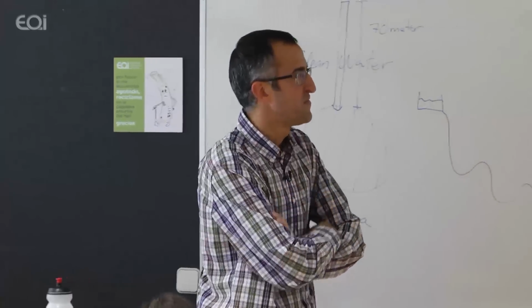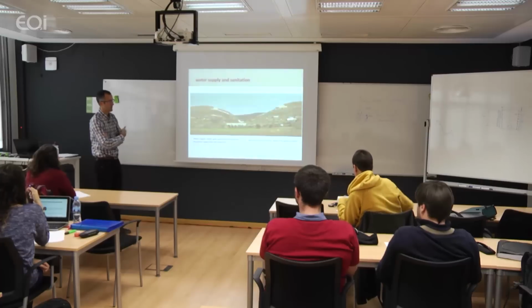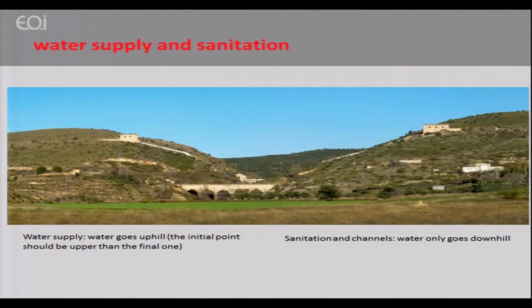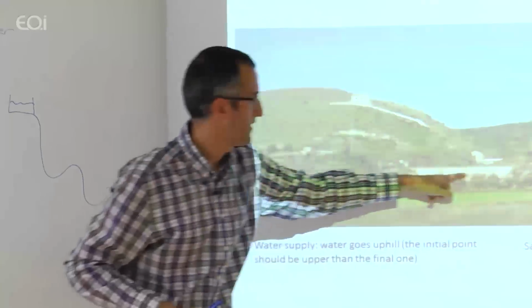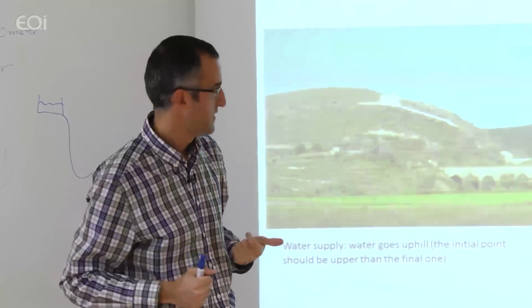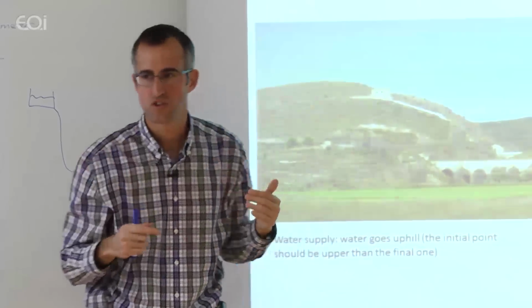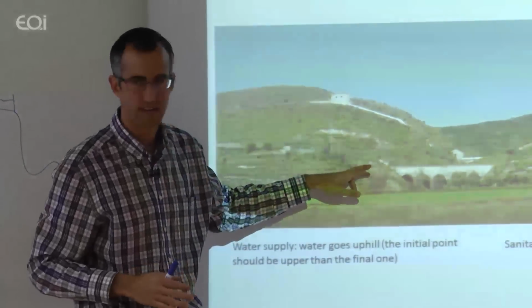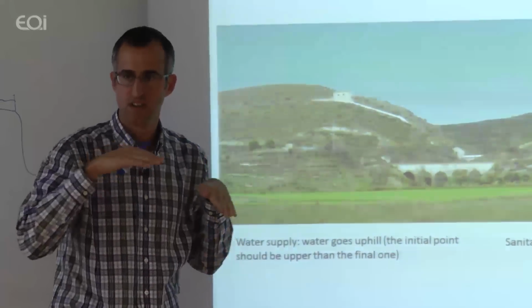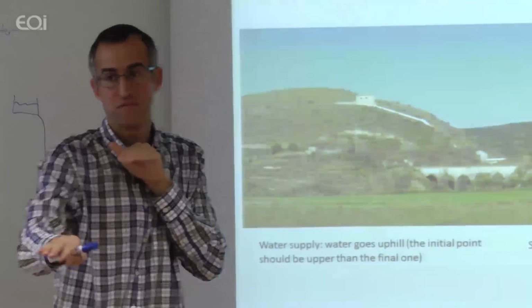And this is very interesting when we see the next one. For example, this is here in Madrid, in Patones, where we take water from the mountains to Madrid. So we take the water from the big dams in the mountains, 80 or 90 kilometers from here, and then we transport this water to the big tanks that we have in the city. All right, and the ones that came before, they installed here the down channel, Canal Bajo it's called in Spanish, and they didn't know about these pressurized things and so on. So they did a channel, and they had here like this valley. So they built this bridge in order always to go down, because they had a free flow system. You always need a slope in order to go down to Madrid.